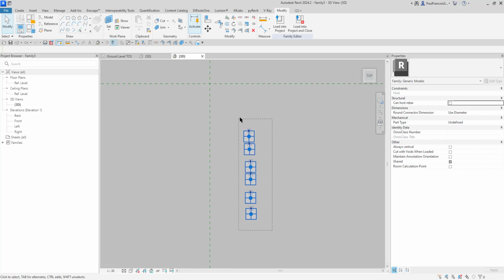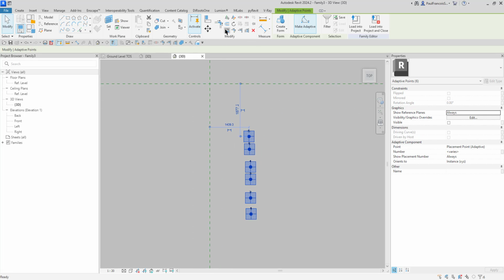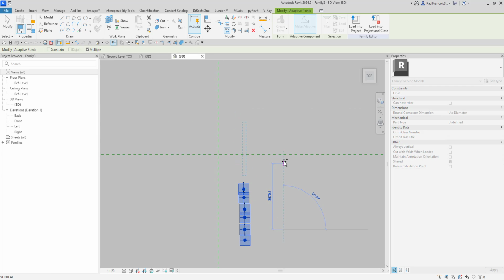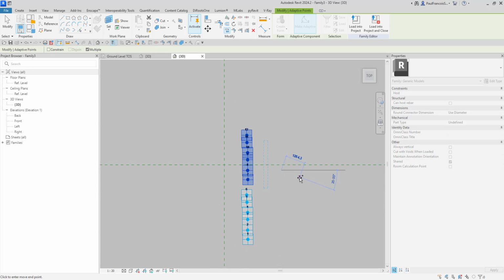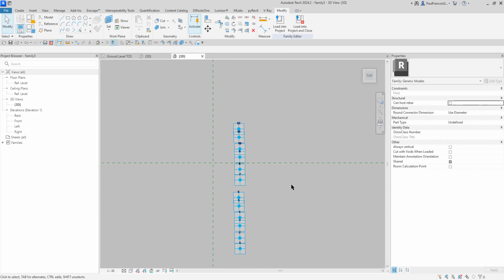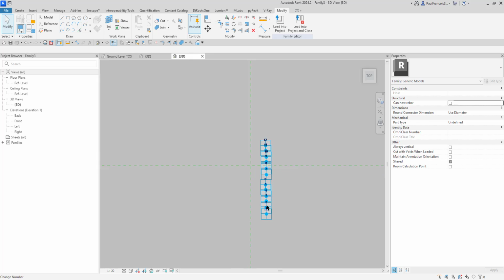It's interesting when you copy them that the points increment alphanumerically monotonically. So there's 6, 7, 8, 9, 10, 11, 12. That's enough for me for now. It's not going to be a long cable or overly complex cable. Of course, you can curve fit these points. So that's quite interesting that, after you've created the family, you could also manipulate that within a project using Dynamo. Sometimes these cables are curved in 3 space, which makes them quite interesting, almost like a parametric cubic spline that you shoot items through.